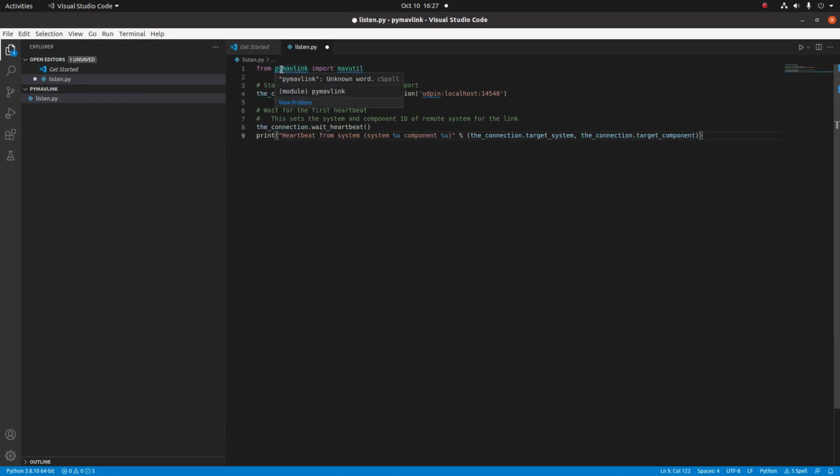So what we are doing is we're using a module called mavutil from Pymavlink, and mavutil has a lot of helper functions for connections and sending messages. So we're going to connect using the mavlink_connection function to localhost, and then we're going to change this to 14551. 14550 is typically the default Mavlink connection stream, but when we launch the SITL, there are two Mavlink connection streams made, and we're going to be using the secondary one because we're going to be using the primary one for our ground control station just to monitor the state of the vehicle graphically and easily.